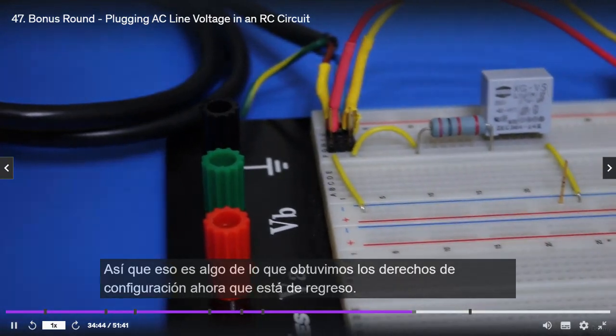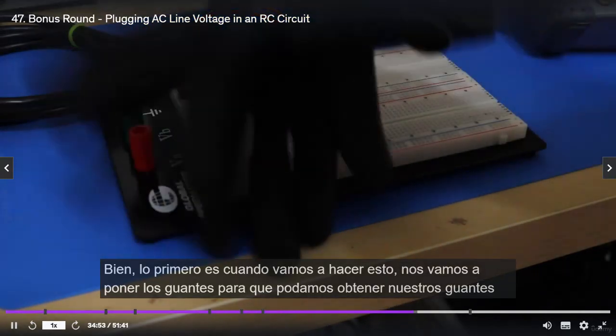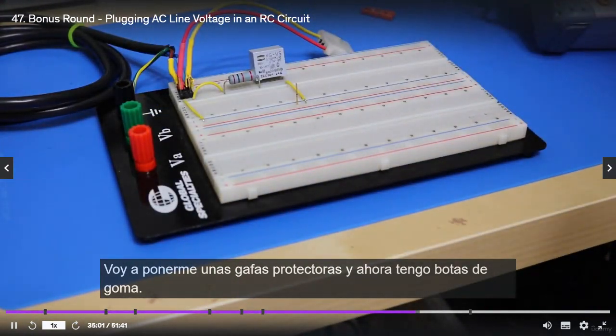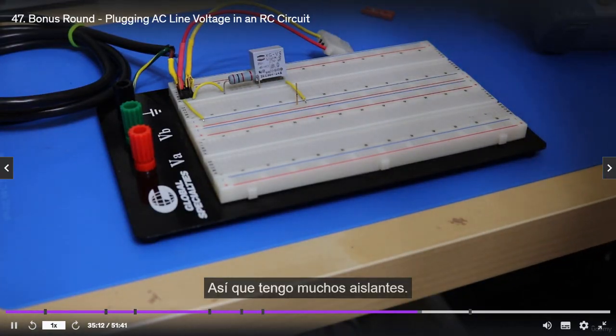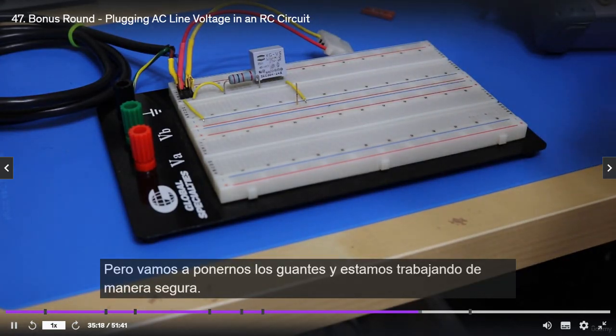Now let's back this off. First thing is, when we do this, we're going to put our gloves on. These are rubber gloves, so I'm going to put those on. I'm going to put some protective eyewear on. And I've got on rubber-soled boots right now, and I'm standing on carpet, so I've got lots of insulators. It'd be better if I was standing on a rubber mat, but we're at least going to put the gloves on so that we're working safely.